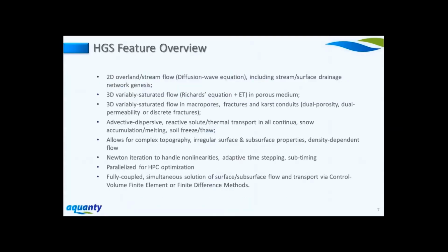This is just a brief overview of some of the features within HydroGeoSphere, or HGS. As I mentioned, we solve the diffusion wave equation, a nonlinear equation that looks a bit like Richards' equation, over the entire land surface, and it includes stream surface drainage network genesis.